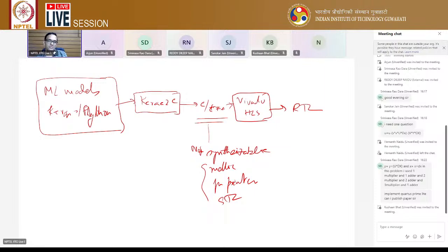As a result, a lot of area was coming. So my suggestion is that after you make this code synthesizable, you reduce the unnecessary array size, right? Redundant array elements. This is something very important. Otherwise, you will not be able to get it.